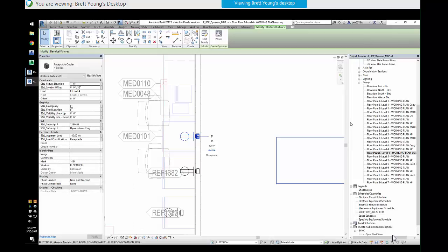So the adaptation of the script would be to add in being able to find the closest wall. I would love that, yeah. And then put it in a preferred location. Right. And the optimal elevation for each piece of equipment. But, yes, there's more to it. And even adding, if there's a unique keynote to each of these pieces, a note that we want to add to all fridges for some reason, or a tag that says plus 46 inches AFF, those can be added with specific information about each of those. We can pass through load. We can pass through a bunch of information to those receptacles to keep it synced up.